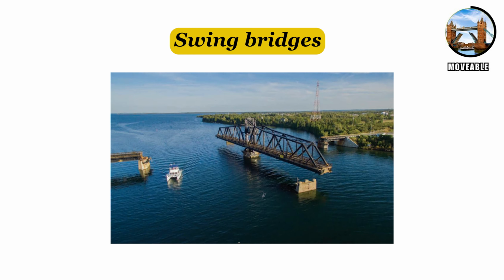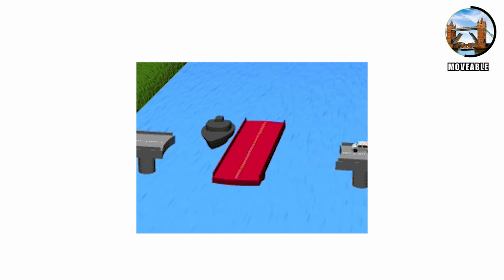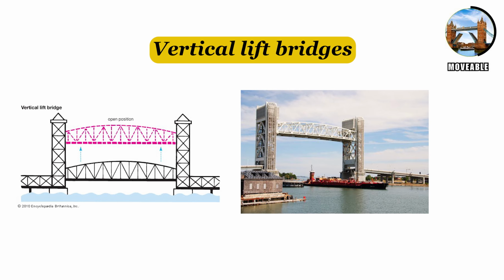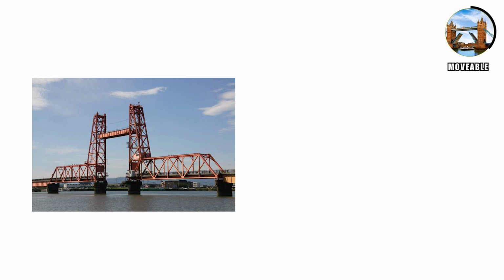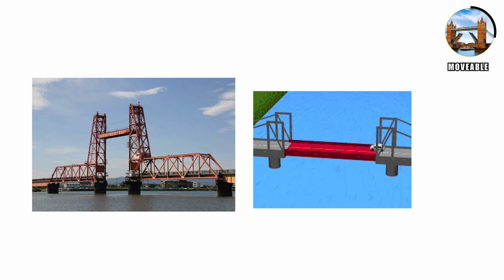Swing bridges rotate horizontally about a vertical central pivot pier, so ships can pass on either side, functioning as two-span continuous beams when closed and as cantilevers when open. Vertical lift bridges raise the entire deck upward while keeping it horizontal like a table, with maximum raising height limited by tower height but minimizing traffic delays by raising only to the minimum necessary clearance for vessels.